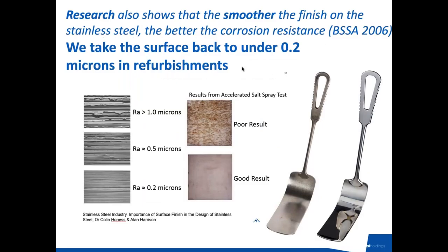Surface finish is often something that gets overlooked, and when we hear quite a lot about validations of sterilizers and washer disinfectors, I'm always amazed that this isn't something that's focused on more, because as this research shows, there's a big variation between corrosion resistance on stainless steel depending on how the surface is finished. So a rougher surface finish performs not as well as a finer surface, which may seem to be fairly obvious,